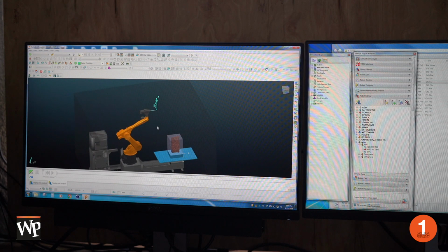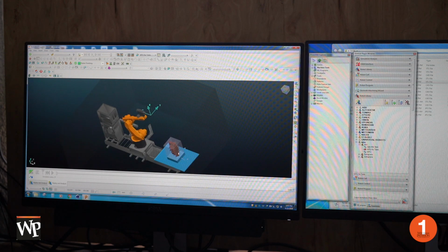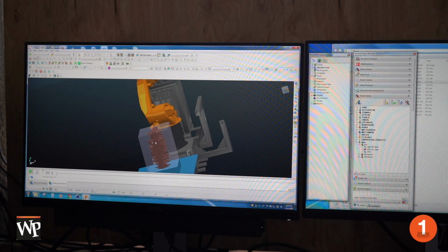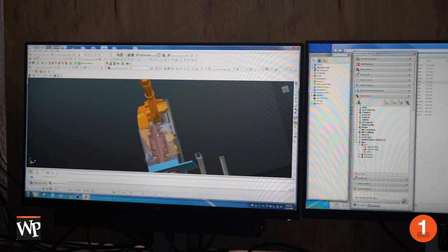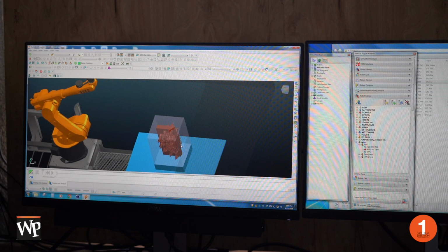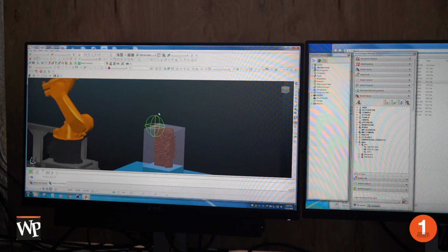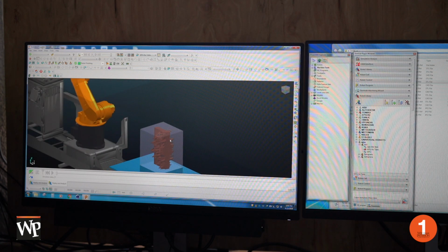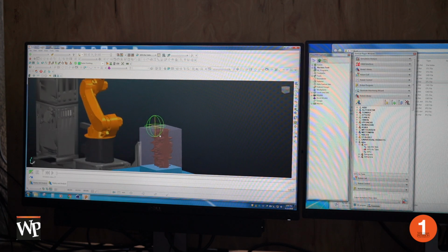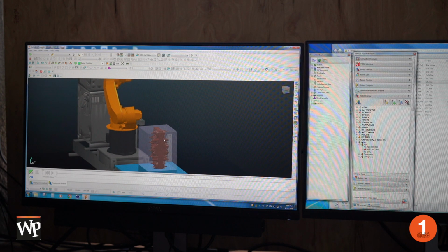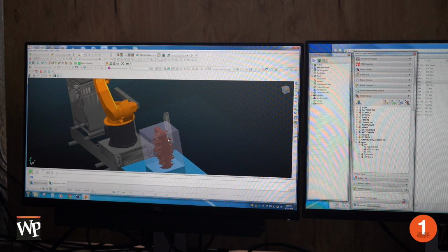So now, to start carving this, we have to see that we have a block that we need to carve down a lot to get to our model. So we're going to start off, and this is true of any kind of carving that we're going to do, with a roughing pass and then finishing pass. And the roughing pass is going to be aimed at clearing as much material as possible. And we're going to want to use larger diameter tools.